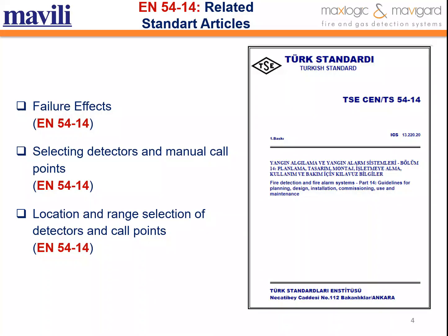Alarm manual call points should be installed in places that can be used easily and quickly by any person who detects the fire. Special instructions given in the manufacturer's data should be observed. Access for maintenance purposes should be considered. And also, EN 54 standards contain that manual call points should be placed on escape routes, all doors of the escape stairs, and all exits that open to the open air. They can also be placed next to special hazards and or firefighting equipment.